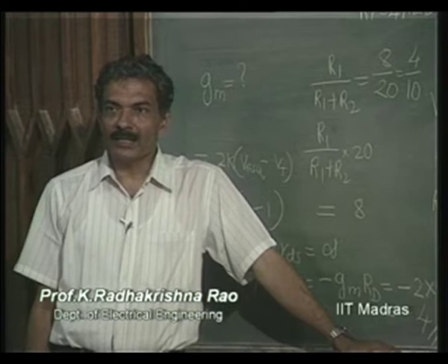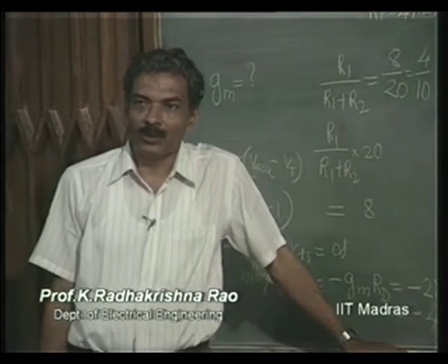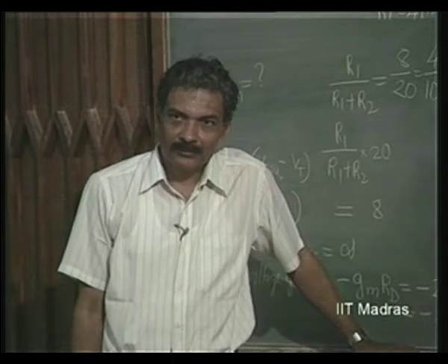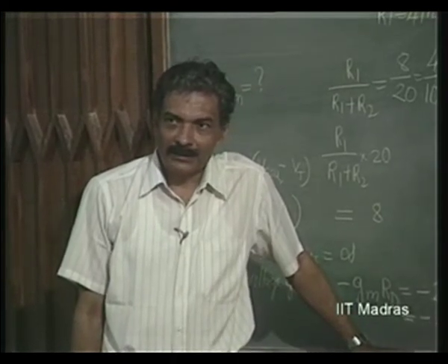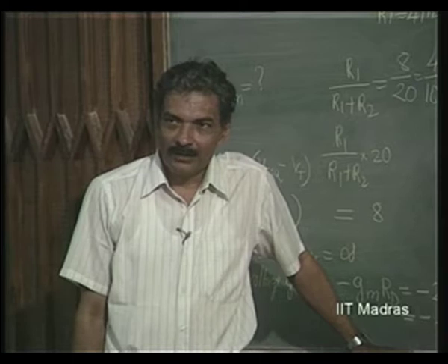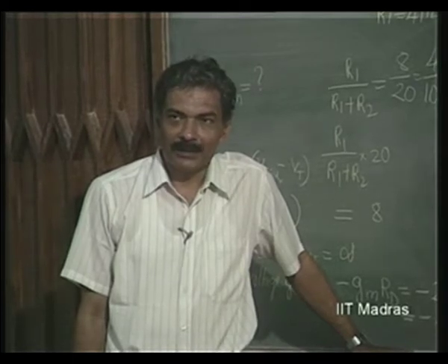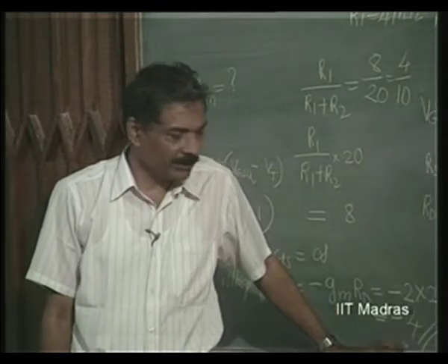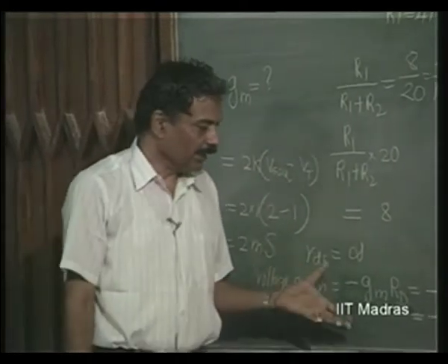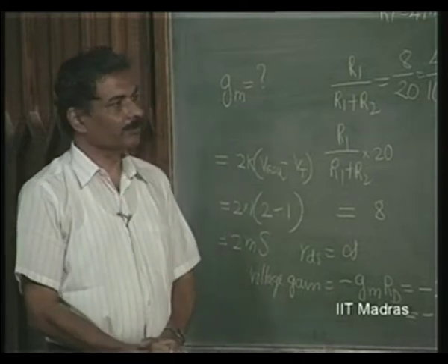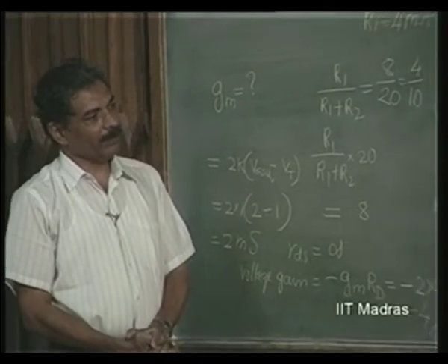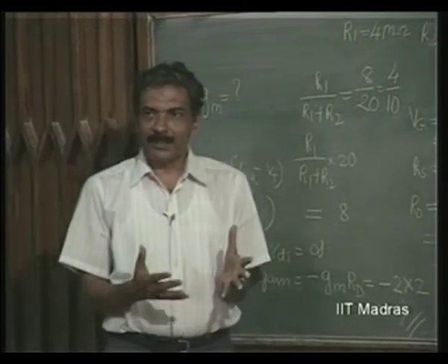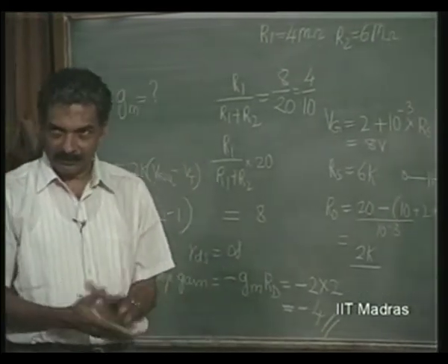So it is very rarely used as what? Amplifier. Field effect transistors are not so popularly used as amplifiers compared to bipolar junction transistors for this reason, that the gain of the stage is pretty low. So, this example illustrates the problem of a field effect transistor amplifier design.